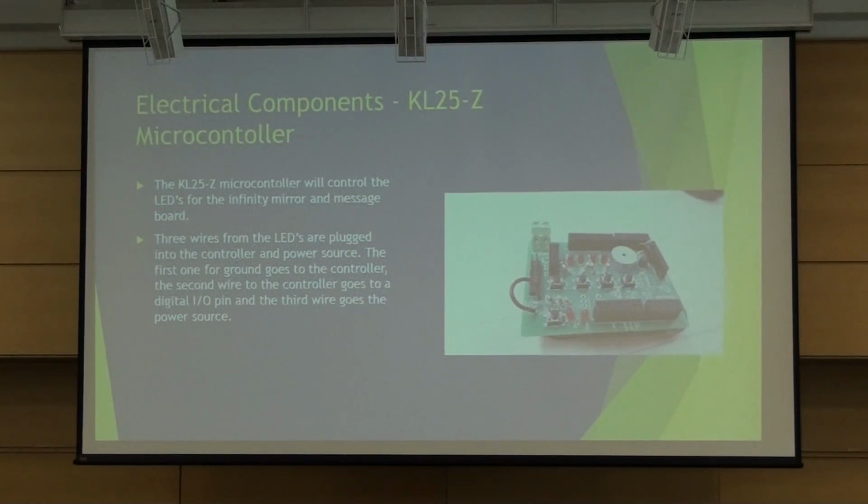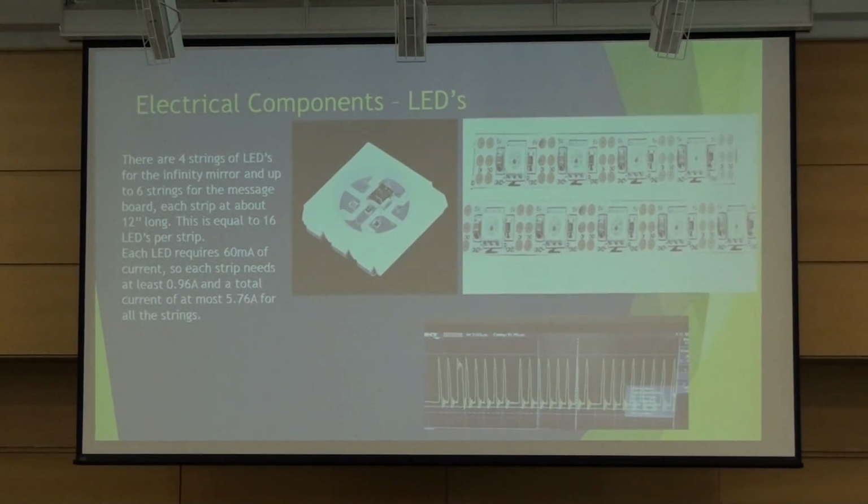So for the first part of the electrical components, the KL25Z microcontroller will control the LEDs for the infinity mirror and the message board. There are 3 wires that go from the LEDs, 2 of which are plugged into the microcontroller. The first one goes to a ground, and the second one goes to a digital output pin. Onto the light emitting diodes.